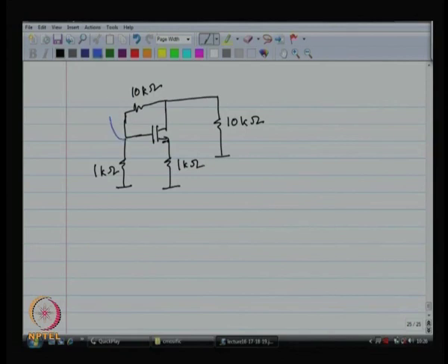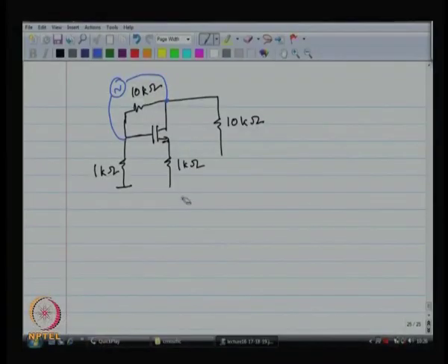And for this you are going to apply your voltage over there across the gate and drain. Now, one nice thing about this is that the 10K is going to come in shunt with everything else, right. So, what we are going to do is, once again we are going to dereference the voltage, the ground. We are now going to call the gate as my new ground.